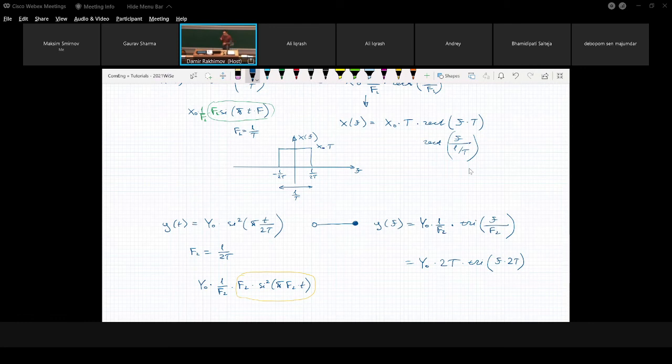You have only one oscillator for the carrier frequency, but you can imagine that you have multiple different channels. Even if you just consider FM broadcasting, you have different stations. Usually inside a receiver or transmitter, you have only one oscillator that generates the reference carrier frequency, but somehow you're able to tune between different channels.